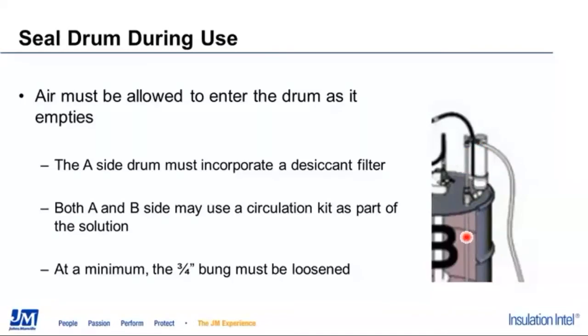At a bare minimum, if you're not set up with this arrangement, just know that when your transfer pump goes into that drum, you've got to at least loosen this 3/4-inch bung so that air can come in and not collapse the drum.